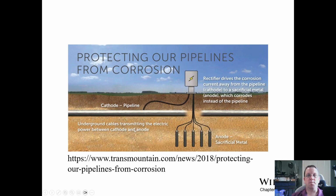So what it's doing is it's basically creating a reversed electrical potential difference between the pipe and the anodes, so that the anodes get corroded and the pipeline gets protected. So you have to periodically replace these anodes. They get worn out as soil conditions adjust and change. The rates of corrosion change, so you have to monitor these stations and monitor what the current it takes to maintain these voltage differences is.